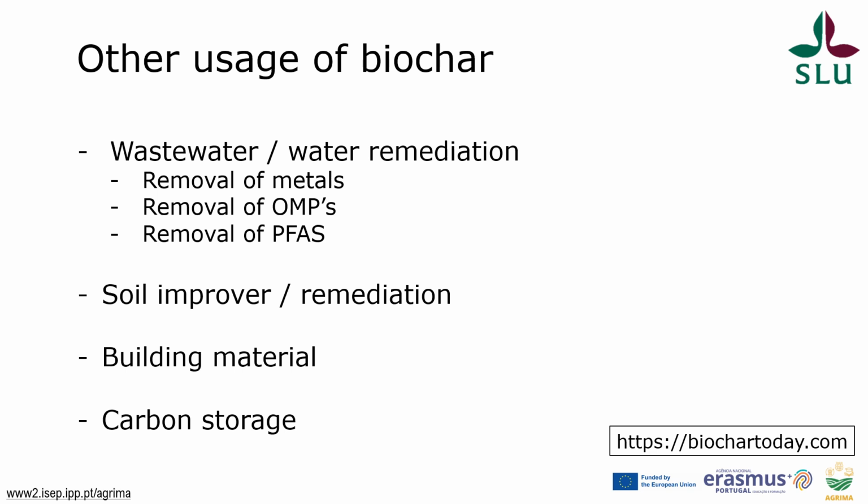Of course, there have been studies on the removal of organic micropollutants in different types of other matrices, and of course the removal of PFAS has been a hot topic. However, PFAS is a bit more tricky, since PFAS usually has a negative head group, so adsorption on biochar is not always the most efficient way to remove PFAS.